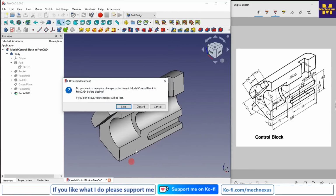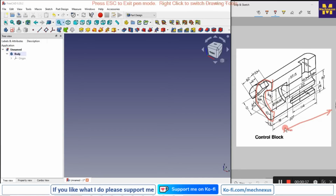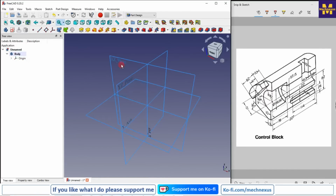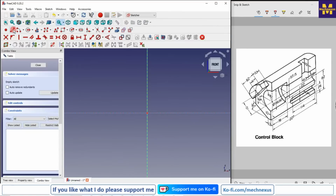So I will close this file and create a new file and a new body. And now first we will make this profile like this, and then we will extrude it to the length of 227, and then we will add the rest of the features. So now I will turn on my origin plane and create my base profile on the XZ plane. I will switch to orthographic, then isometric, select this XZ plane and create a sketch.